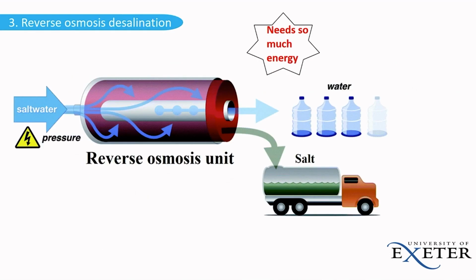One of the common desalination methods is reverse osmosis. You can see a schematic of a reverse osmosis desalination unit here. Reverse osmosis is a process where pressurized seawater flows through a filter, separating fresh water from saline water. By adding an external pressure to one side of the filter, clean water will flow to the other side. The products of the reverse osmosis process are fresh water and brine with high salinity.